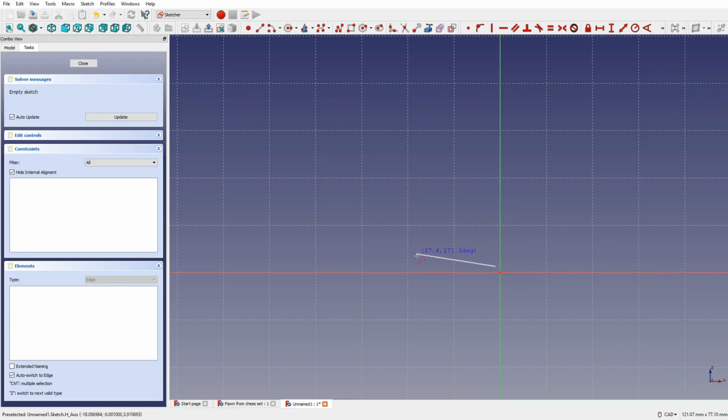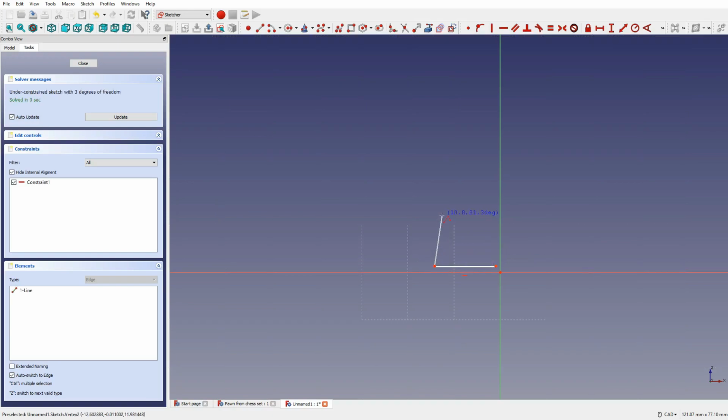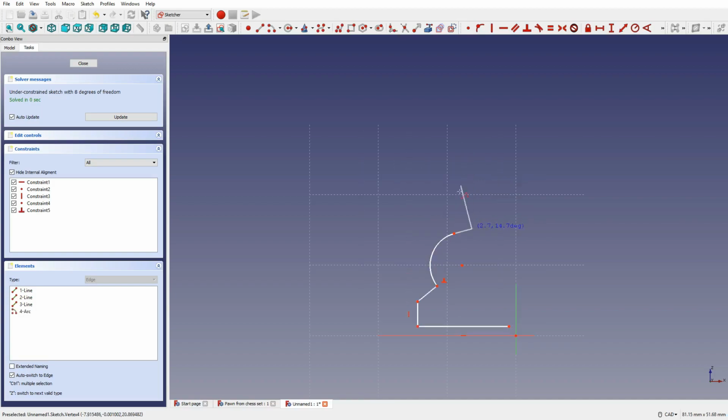So I'm going to click down here, make sure it's just sort of rough. One click there. We'll do a little click up. I'm then going to come across just roughly. I'm going to click the button M once, twice, three times, four times, and it's going to make a radius tool. I'm then going to place that there roughly. I'm then going to change it again back to M, M, so it gives me this straight line. I'm going to move that up, sort of like so.